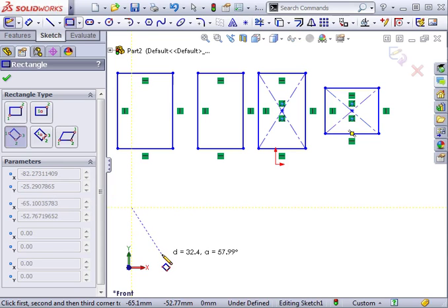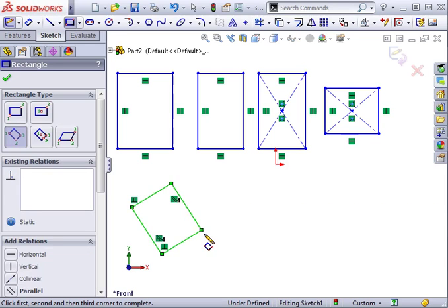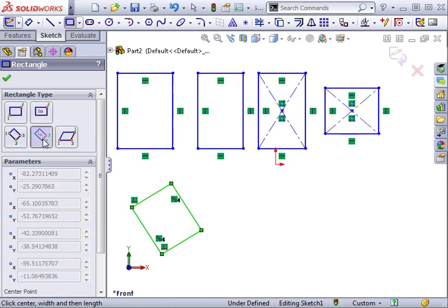With the regular circle tool activated, I'll click to locate the center, move the cursor, then click again to define the radius of the circle. The click-drag method works as well. Click to define the center, hold down the mouse button, and release it to define the radius. Next, I will switch to the perimeter circle. As you can see from the icon, I need 3 clicks each representing a placement of the outside of the circle.